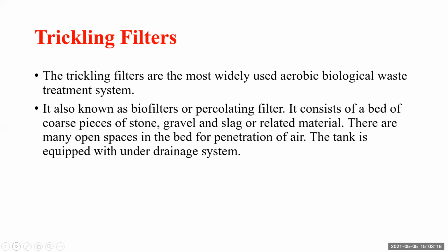Okay, so there are too many open spaces in the bed of this stone or gravel or slag for the penetration of air, and hence aerobic conditions are easily maintained so that organisms in presence of oxygen can degrade the organic matter. The tank is equipped with an under drainage system to remove the treated effluents.